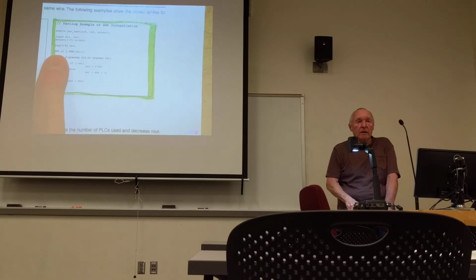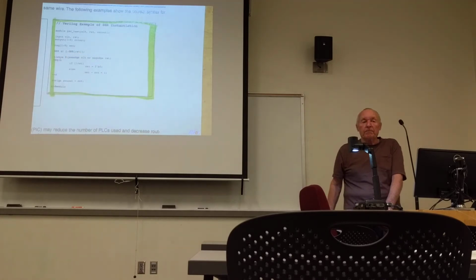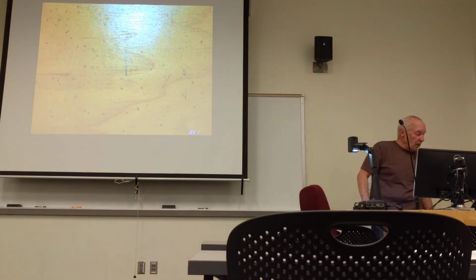It's a library component. Its name is GSR, all uppercase, so I just instantiated it, connecting by name to GSR the reset signal I want to use. This will generate a pulse on RST when the FPGA powers up. So there's a simple way that you can get a pulse to initialize your design.